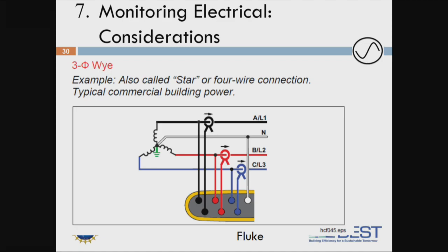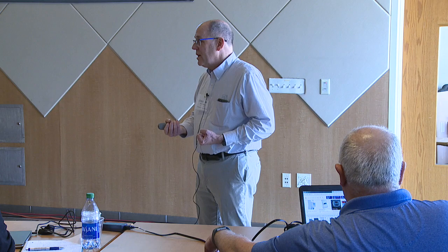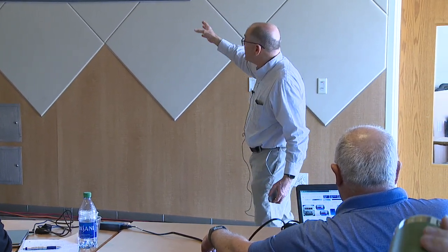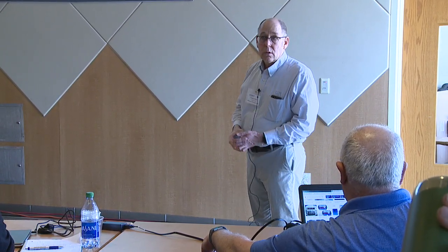Making sure you wire these up correctly is really important because this can screw you up in a heartbeat. When I was doing it, I didn't have readouts on the equipment, so I had to hook up a laptop and check it, and you're under time constraints. If you set this up wrong, you come back a month later after you've had your extreme events where you want to really tell your client what's happening, and you messed up the wiring, you're out of luck. Today it's much easier with readouts and things like that, but getting this set up correctly to begin with is really important.